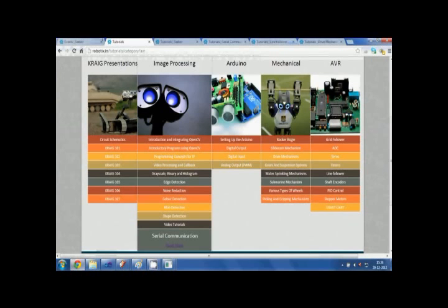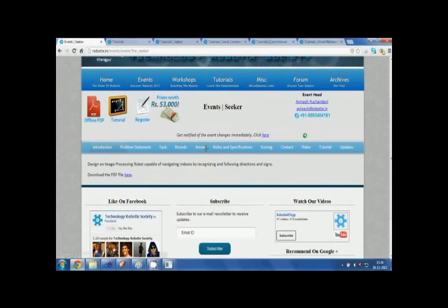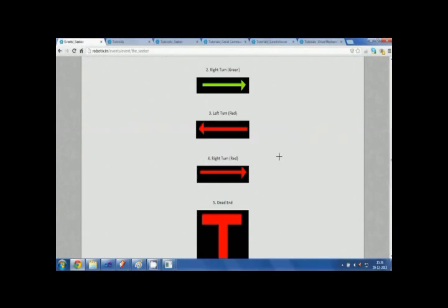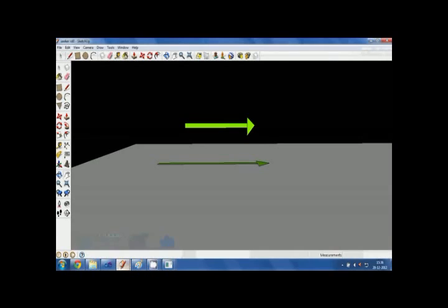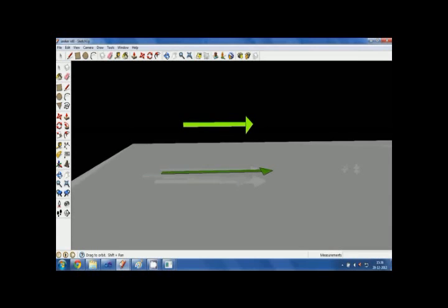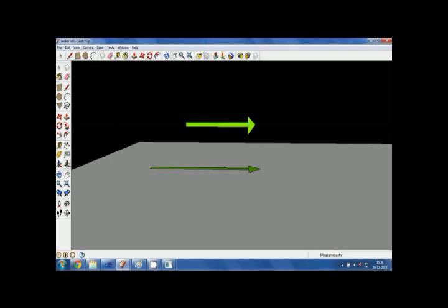Just to be sure, let's have a look in case you are doubtful at this arena tab. Yeah, left, right, turn, dead end, stop. These 6 signs in round 0 that can appear there will only be green or red. So you can always check if there's a green or red blob appearing quite prominently in the sights of the robot. And at this point of time you can stop your lane detection, because you see there's one line here but there's no longer another line detected. So maybe in your code, once you find out that 2 lines are no longer detected, assuming you ignore the top half, if you find only one major maxima, that means it's time to make a turn or to do something of that sort.